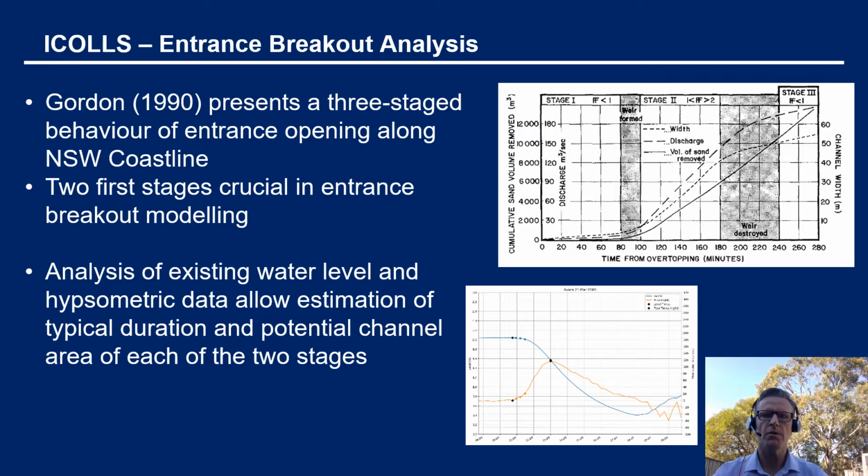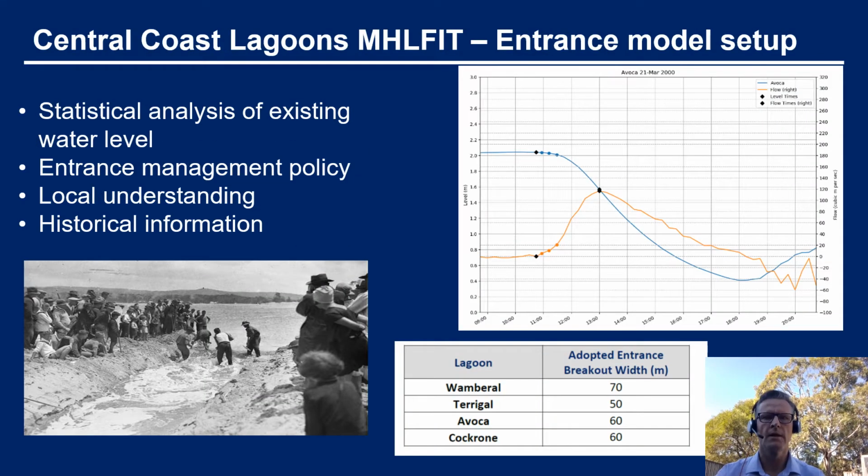We are lucky to have a plethora of data for these lagoons, and we're able to develop automated techniques to analyse the data. Some of the information was water level data to assess typical opening durations and widths. The entrance model is based on the statistical analysis of the existing water level, tide, wave, and rainfall data.